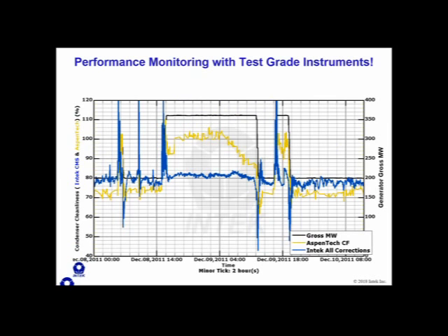Yesterday I covered the essentials for performance monitoring, the instruments that are used for that, the formula and validation of the standard parameters. For example, we covered the importance of the proper location of pressure taps, making sure they're down near the bundle, not up near the turbine. Using pressures and temperatures to validate the condenser pressure measurement. So one that we showed yesterday was using the hot well temperature or exhaust pressures or some other pressures and temperatures that you might be measuring on the condenser to validate the pressure that you're using for performance calculation.